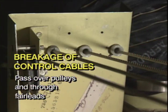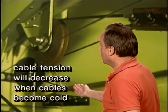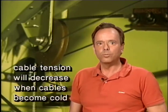All right, now the next thing we want to talk about is a cable-operated control system of an all-metal aircraft that does not incorporate a temperature compensating device, and it's been rigged to the correct tension in a heated hangar. Now, if the aircraft is operated in very cold weather, they're going to ask you what will happen to cable tension in cold weather. Well, in very cold weather, cable tension will decrease when the cables become cold. And the reason for that is the aircraft actually shrinks more than the cables do, so cable tension will decrease when the aircraft structure and cables become cold. It's both of the two combined that become cold.